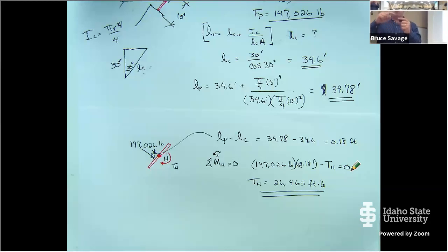The flow tries to move around this tortuous path of those little teeth. It creates little head drops, little pressure drops rather than a big pressure drop, and hence it doesn't cavitate, because it takes the pressure down in steps. So probably more than you cared to know, and then there's a few other valves, but for a low level outlet dam,